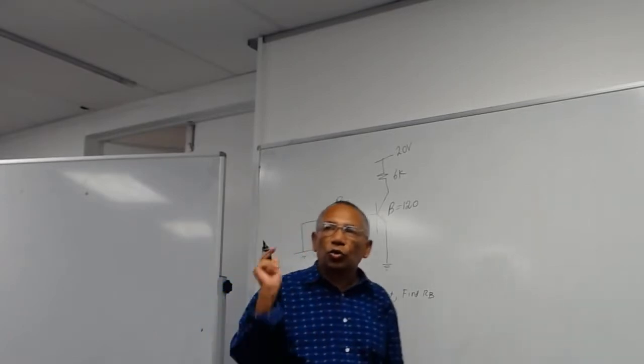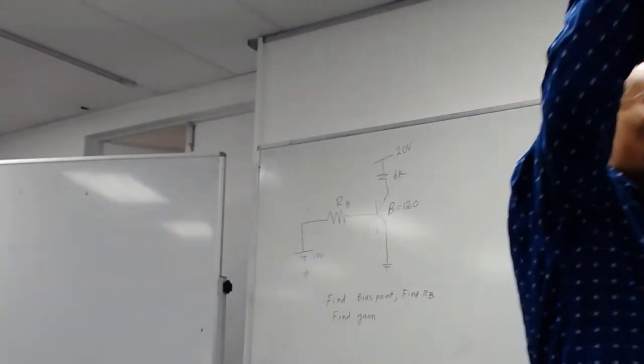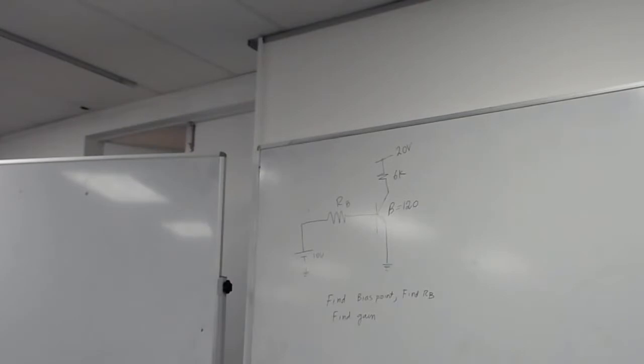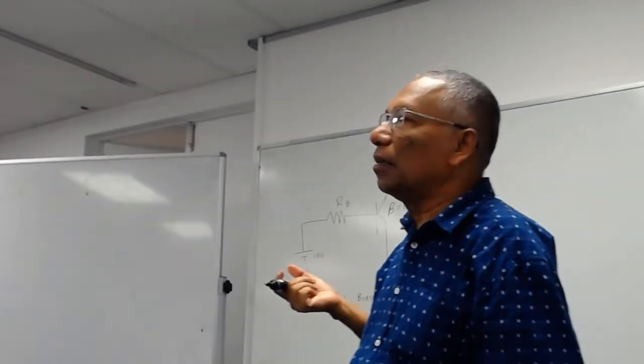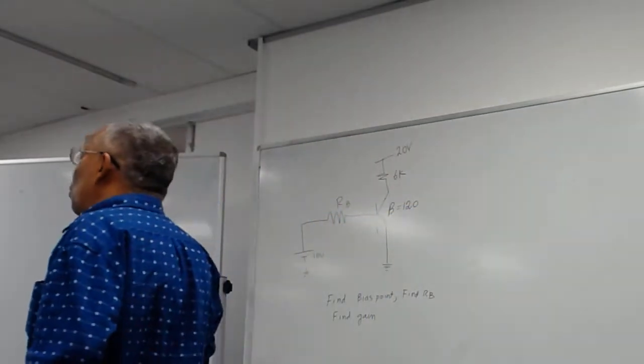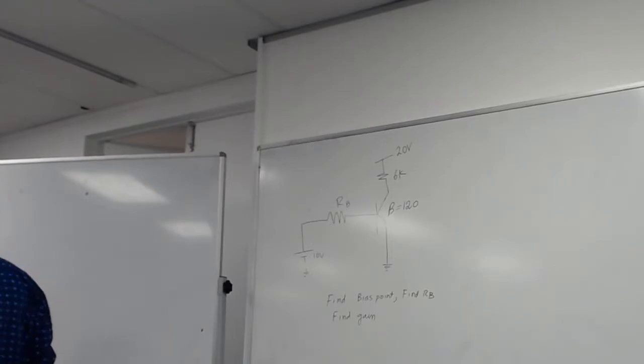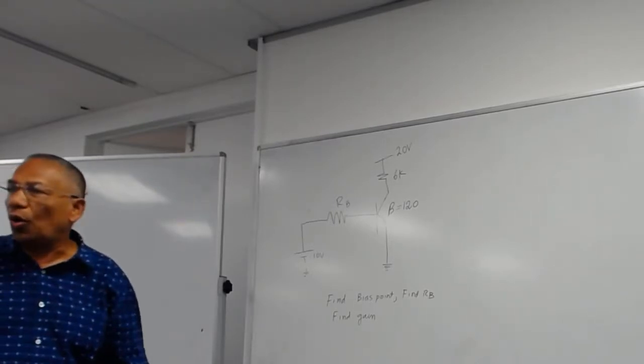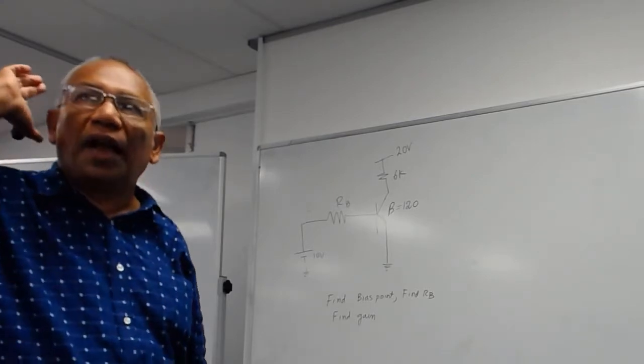That means to find all of this, you have to go straight actually from the IC set and DC off, that is when you saturated, to get those 2 points, and then draw the load line, find the middle point, find your bias point, find GM, then draw the AC equivalent circuit, then insert the T model, then do the AC analysis. So everything that we have done a little while ago algebraically, now you have to do it in arithmetic.